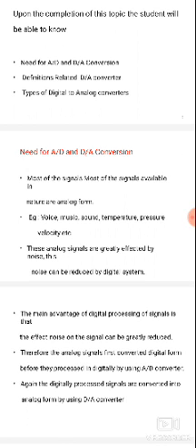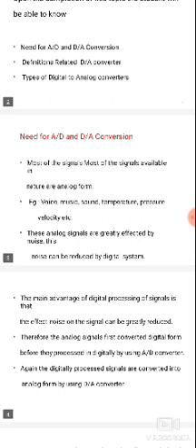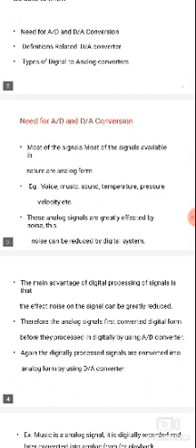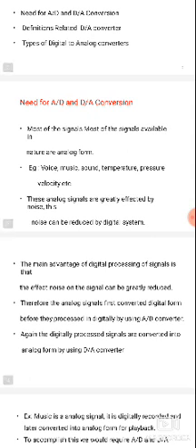Also the instrumentation amplifier. The instrumentation amplifier is designed with 3 operational amplifiers. The 2 operational amplifiers work as buffers. A buffer is used for input impedance purposes. A buffer type of amplifier matches the input impedance, and it increases the input impedance. Next, it is used for measurement and test equipment purposes. Next, the differences between op amp and instrumentation amplifier were also completed. The instrumentation amplifier's main application is in biomedical applications.